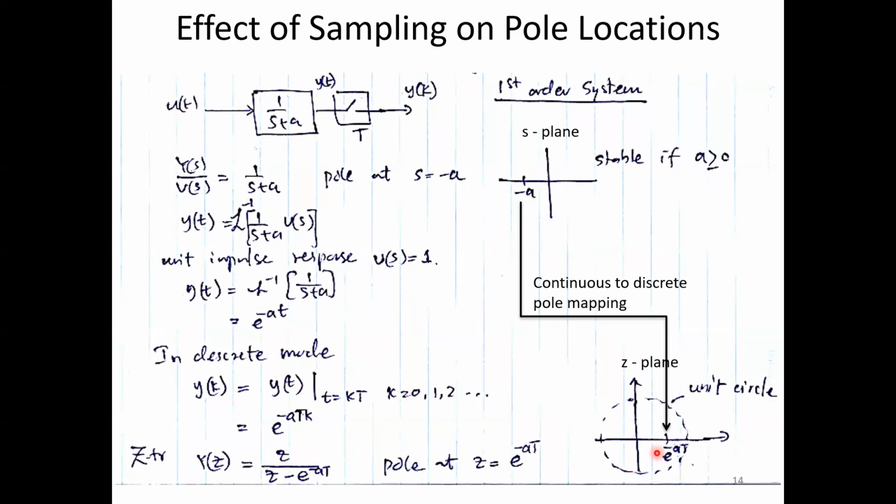So in this slide, we have both worlds connected very nicely, the continuous time thing and the discrete time thing. What you need to understand here is that the continuous time plant is not going to change because of the discretization. The plant doesn't change because of the sampler or whatever. We take the reading through the sampler, and then we need to judge how accurate the signals coming out of the sampler are, how frequently we are getting the samples and so on.